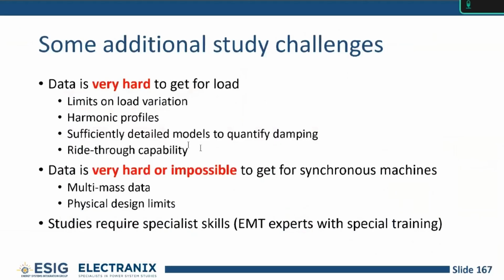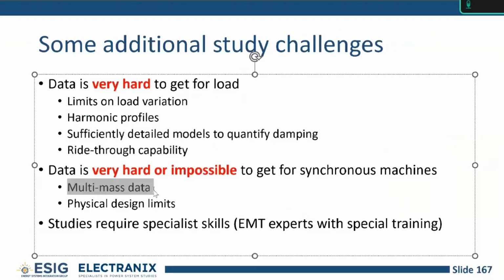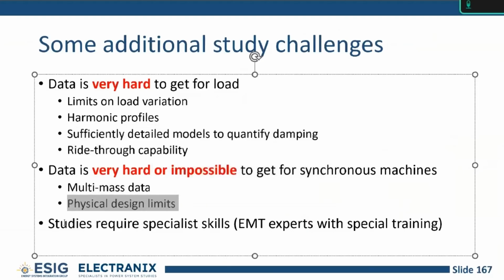It's also very hard to get ride-through capability for the loads. Data is very hard or impossible to get for synchronous machines. Multi-mass data you may be able to get, I would say that model, so you can at least look at what the torques look like, but the physical design limits are very hard to get. And the studies now require specialist EMT study capability. So it's not a traditional one, you have to be an SSO specialist.